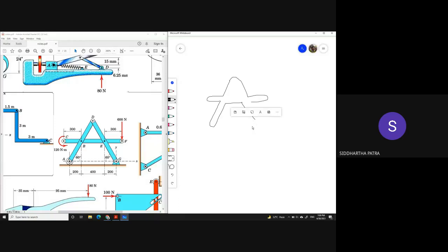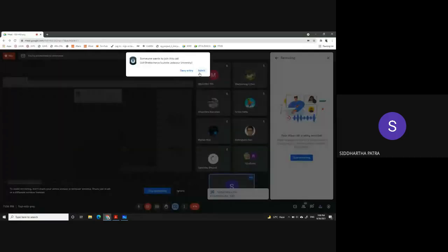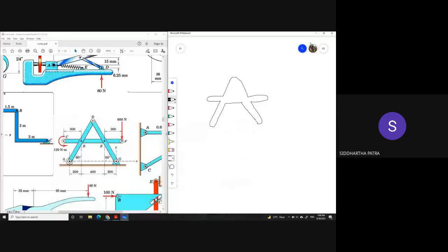So if I look at it component-wise, where I'm looking at individual rigid bodies, they are in equilibrium, and also the entire structure is in equilibrium. So I can write equations of equilibrium for this whole structure. Now for that I need the free body diagram for this structure.